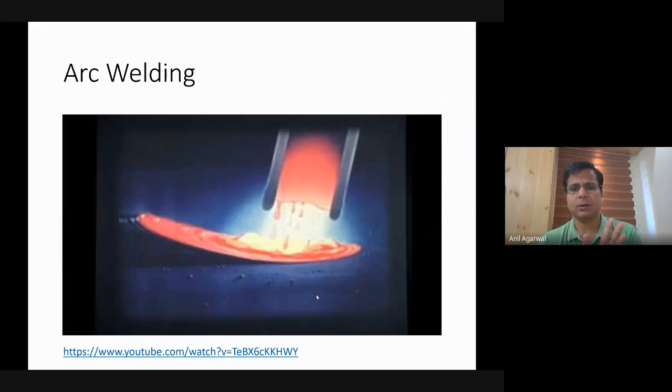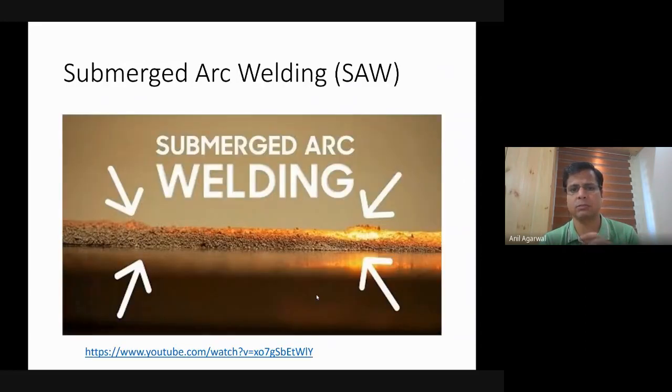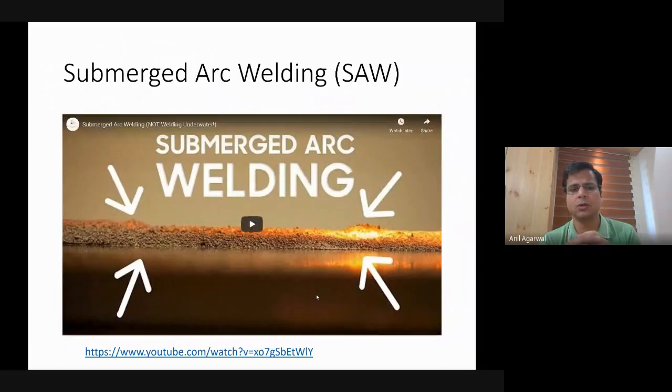Then we had seen a couple of videos. One video was about what the arc welding process entails. Then there was another video about submerged arc welding in particular. There you might remember seeing what happens once this flux is deposited. It keeps fusing, or oxidizing, as the welding process goes on, and after a certain length has been welded, it automatically starts to separate from the weld. As it cools down, it starts to bow a little bit and separate, and sometimes it is very fragile, so it does not need a lot of effort to be separated from the final weld.